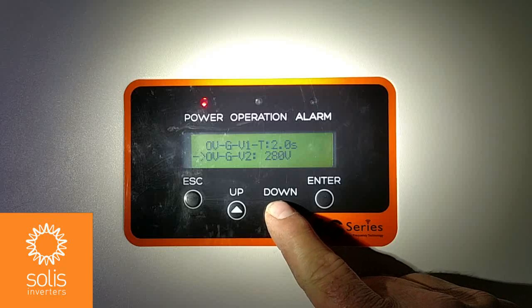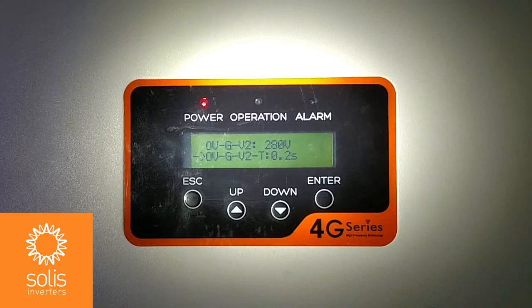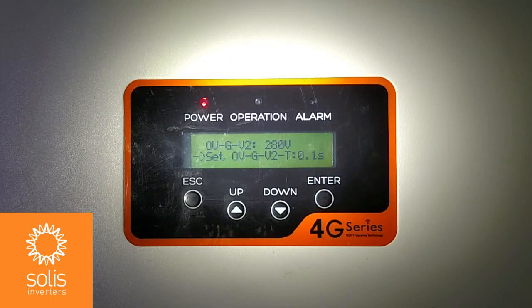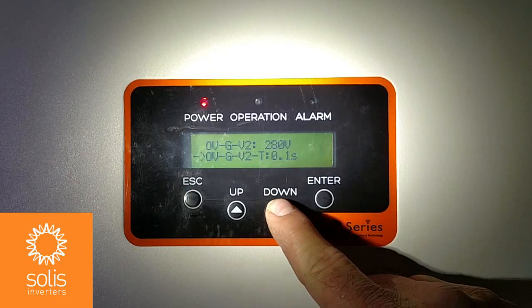So we can now go down to the overgrid voltage absolute limit, and this is set to 280 volts, and we have that set to 0.2 seconds. We want the inverter to trip out very quickly if it ever hits this absolute limit. IEEE gives us some guidance around 0.16 seconds, so we could actually enter this menu and adjust that down to 0.1 seconds to be well within the IEEE limit. So escape again out, and then we can go down to the next setting.